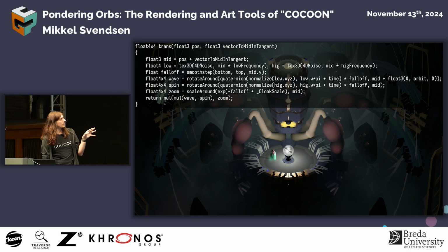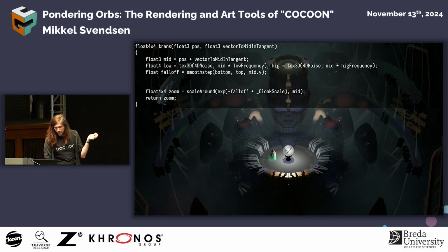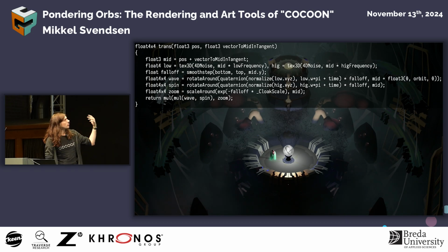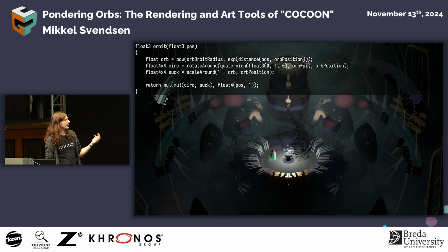That center is put into the mesh by simply adding the delta from each vertex to the center to the tangent of the mesh data. This is because then the engine's built-in skinned mesh compute shader will just animate it for us, and then it works on skinned meshes as well, and now we can do everything in the vertex shader instead. Now, it first scales down towards the center to separate out the particles a little bit, adds a little bit of random noise to pick them apart and make them look all noisy, and then they each turbulently orbit around a random point at a random speed, and then they of course all orbit down towards a point.